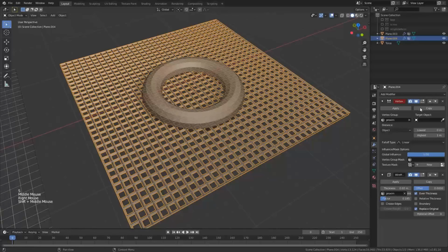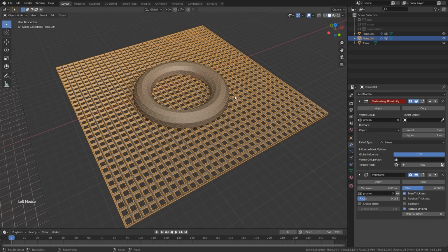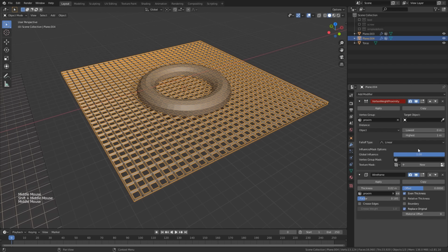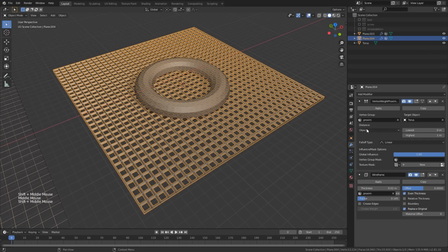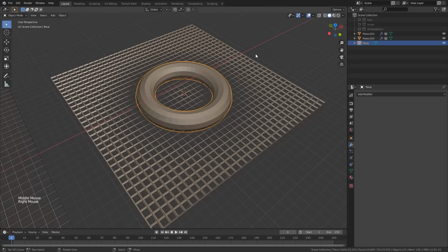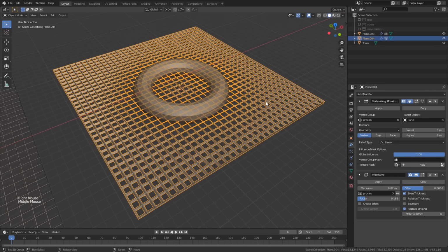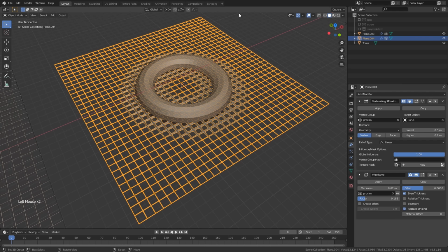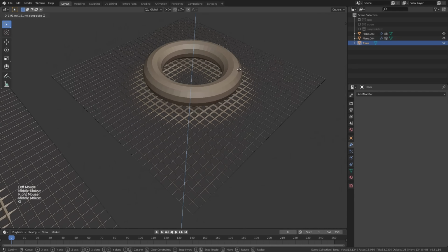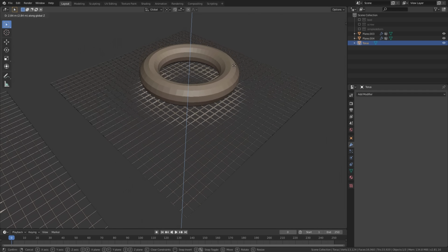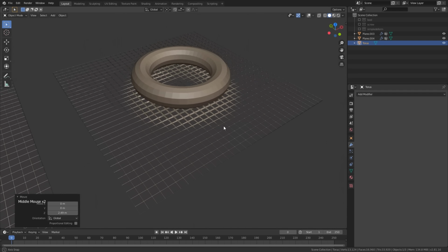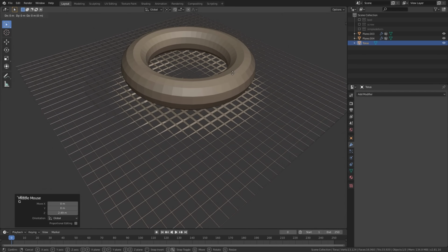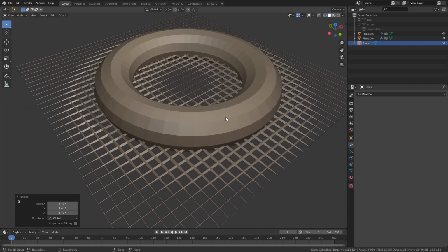Now as the name suggests, what this modifier does is it works in approximation with another object. Like let's say I pick the target object and define this torus, and change the distance to geometry. Now you can see, to increase the visibility more, I'll change these parameters a bit. Now what's happening is, when this object moves close to this object, the weight paint of these vertices is becoming stronger, and it's working in approximation with this object.